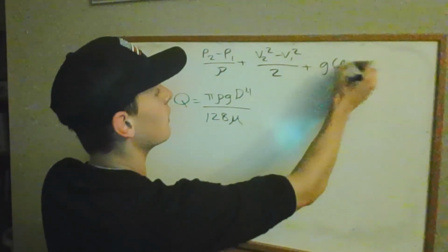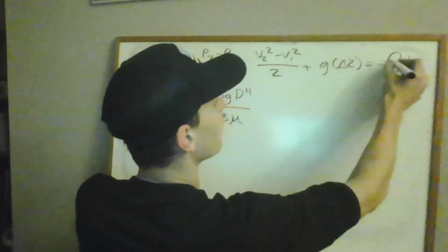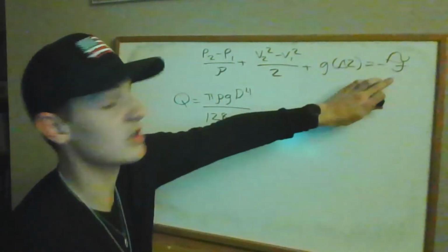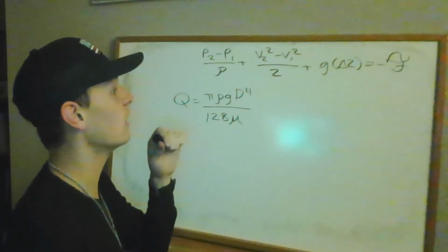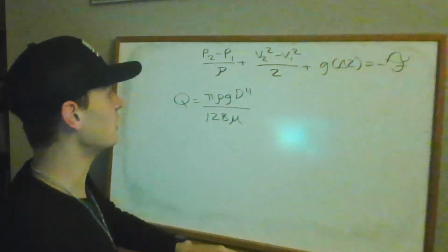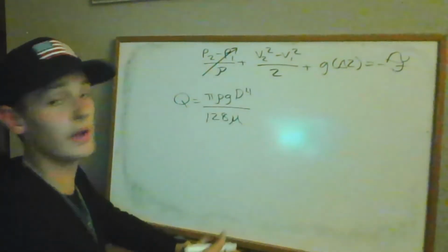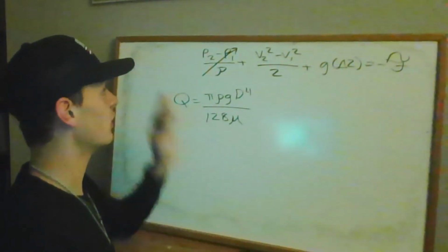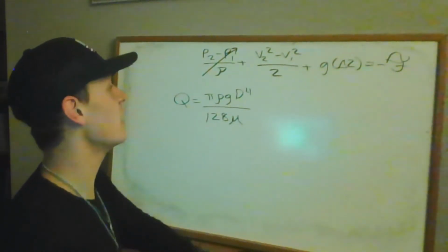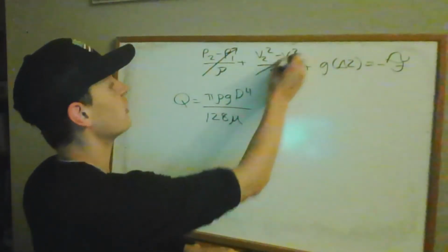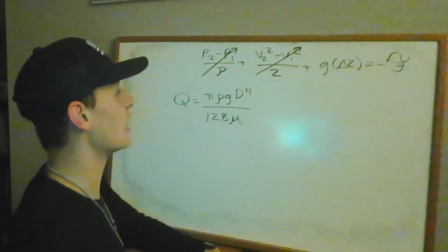This fancy F always gets me, but that is the frictional heating, and that is not negligible in this case. Here, we don't have to consider any change in pressure. And there's also no change in velocity because the cross-sectional area of this cylindrical pipe is constant.